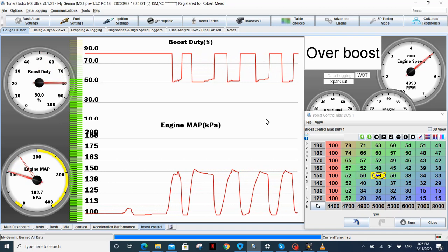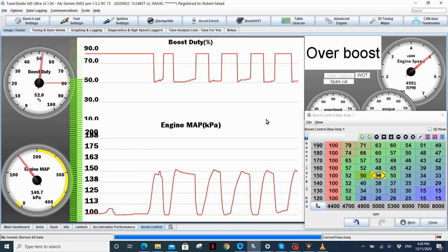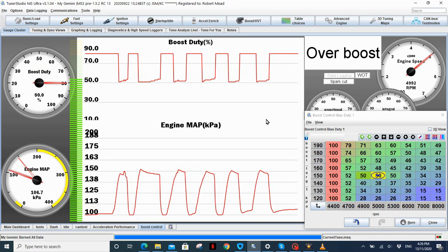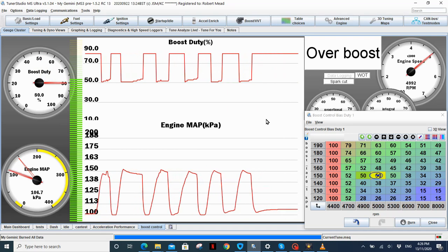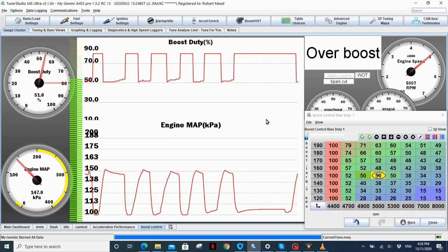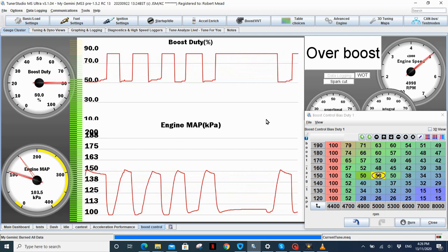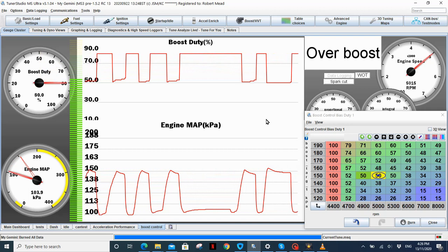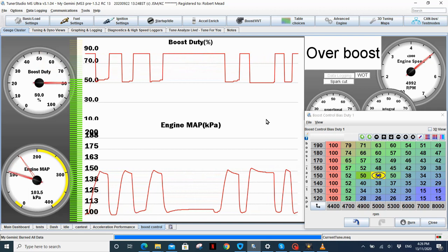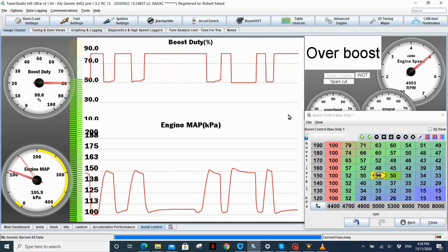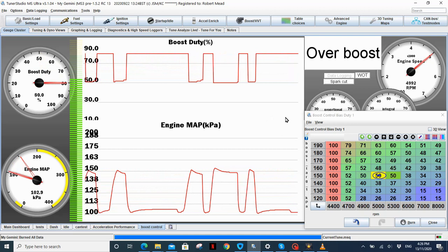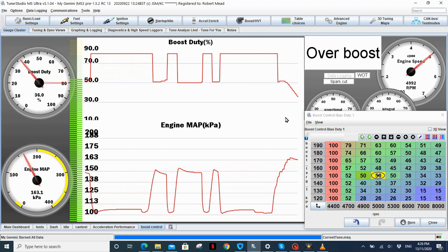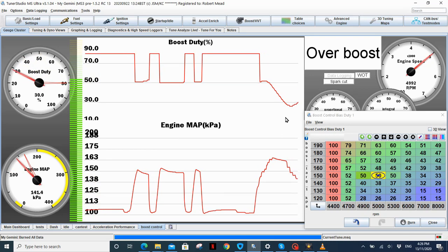And if you can't get away with it, then maybe you can just pull 5%, 3% maybe out of your bias duty table, so by the time it is raised up a touch, it's hitting where you need it to hit. So there you go, that's a hot tip there. So let's just have a look at the PID doing its work anyway. So we'll come up, we'll give it a bit of an error signal, and you watch it drive there.